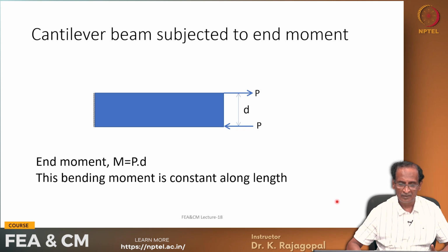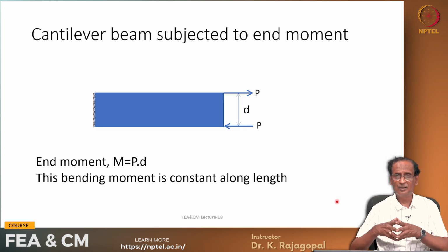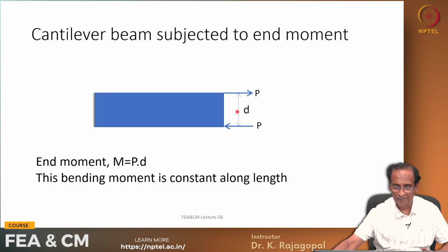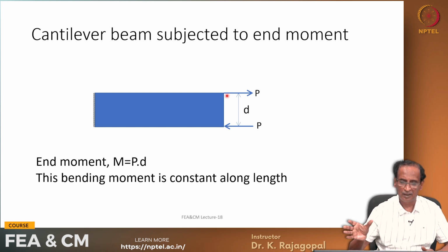In our continuum elements, we only have the facility to apply forces either in the x direction or y direction, but then how do we apply a couple or moment? What we can do is apply forces like a couple.